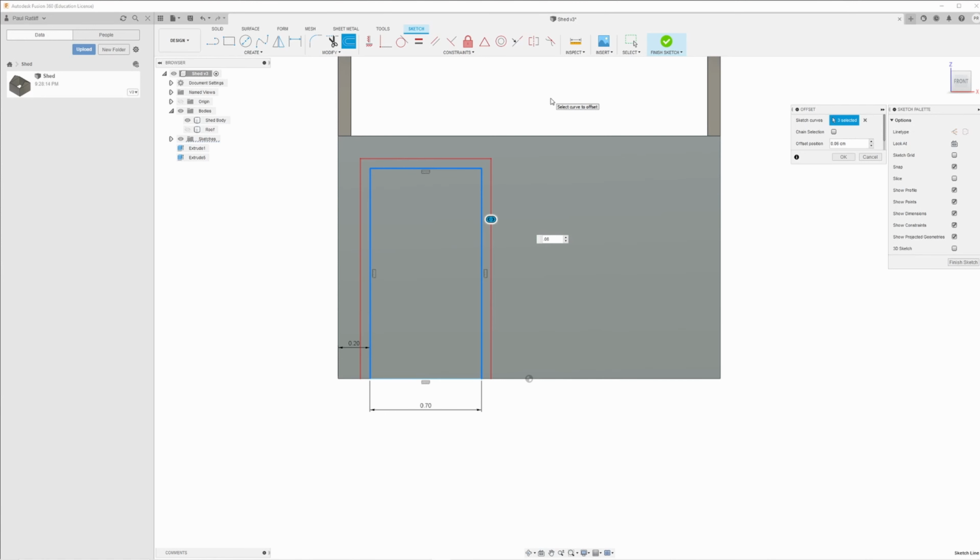That's another thing, you guys, we're designing in N scale, and you have to exaggerate some of your items in N scale just to get your 3D printer to actually be able to print it well. If you try to design it to true N scale, some of these items like this door frame, you're not going to see it, or it's not going to print very well at all.